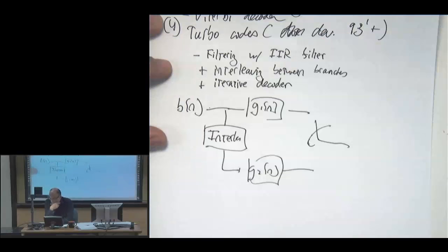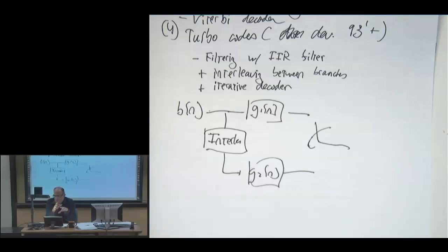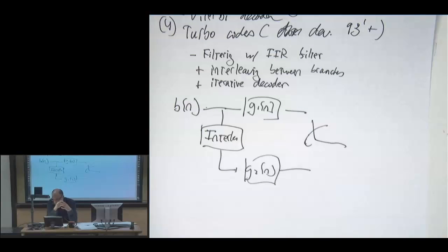And so it's a special decoder. It ends up being about 4 times more complicated than the Viterbi algorithm, but it allows you to essentially use part of the data to make a guess. And you take that guess, and you use the other part of the data to refine your guess. And you take that refined guess, and then use the original piece of data to refine your guess further. It turns out that by designing this interleaver and these polynomials correctly, you can actually improve each time up till some point and get very, very low error rates. And so these turbo codes, in theory, get very, very close to the fundamental best that you could do.